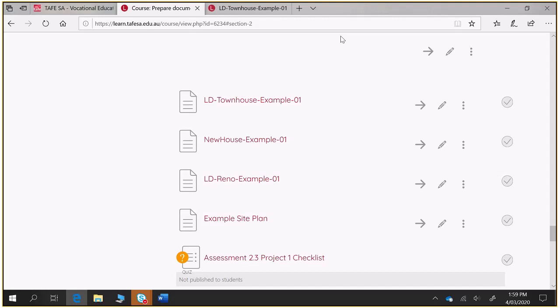So I'm just thinking another way to express that is, say for instance you want black butt. Could you say black butt or an alternative that meets the following requirement, non-combustible or combustibility in the range of X? Yeah, well, you can say hardwood timber to be selected from table F of AS3959. Right. Yeah. I mean that works better for me. It is an objective measure of the key quality. Yeah.